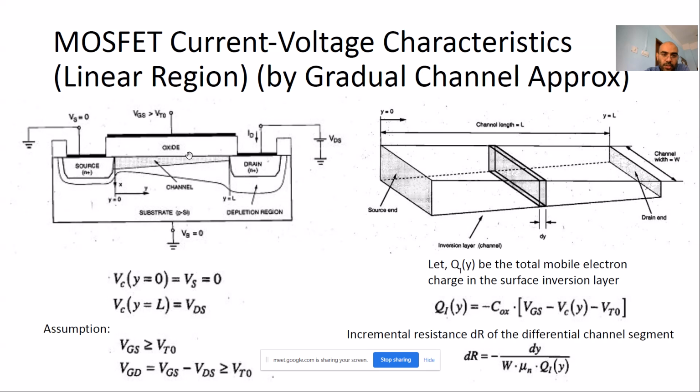Okay, so this is what is happening actually. What Abhinav was telling is very right. So in simple terms, if I try to explain, consider VGS, let's say VG at a certain voltage, let's say 2 volts. Now you see the source is at 0 volts and the drain is at some small voltage, let's say 1 volt.